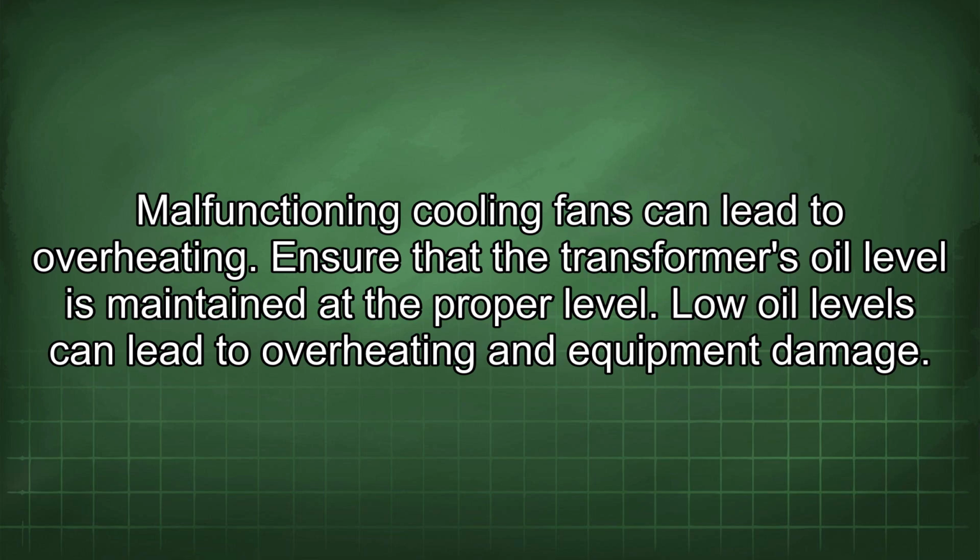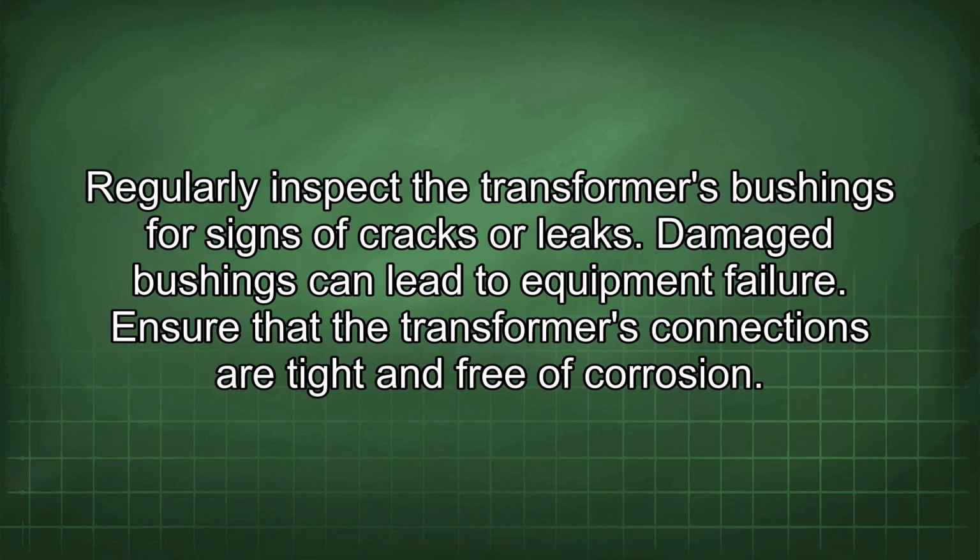Ensure that the transformer's oil level is maintained at the proper level. Low oil levels can lead to overheating and equipment damage. Regularly inspect the transformer's bushings for signs of cracks or leaks. Damaged bushings can lead to equipment failure.